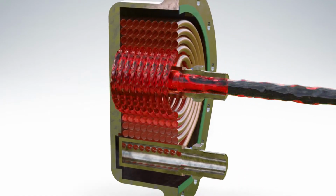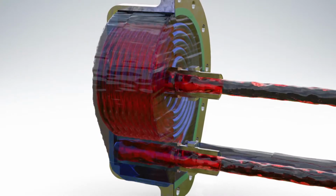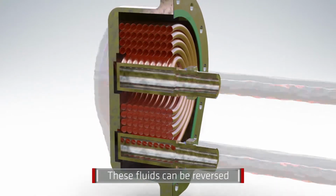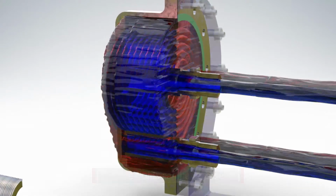You can see the hot side fluid inside the tubes and the cold side fluid outside the tubes in the shell side. These fluids can be reversed with the cold fluid inside the tubes if that's what the application requires.